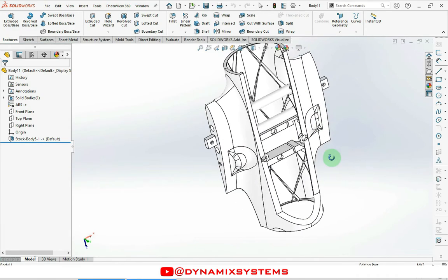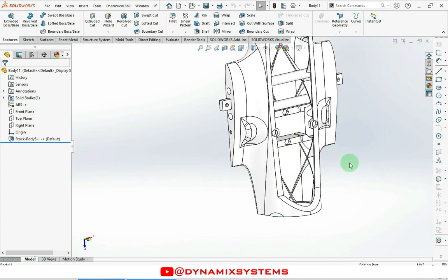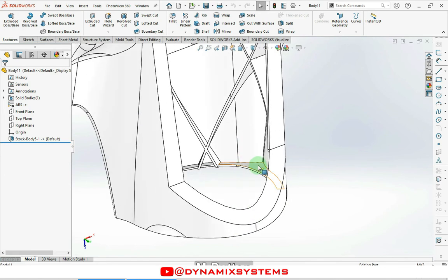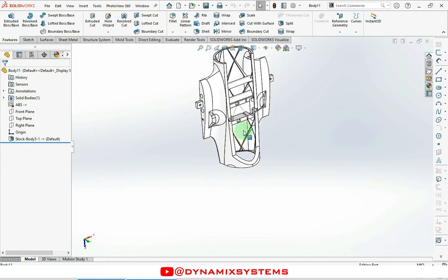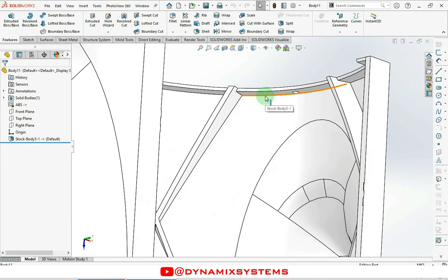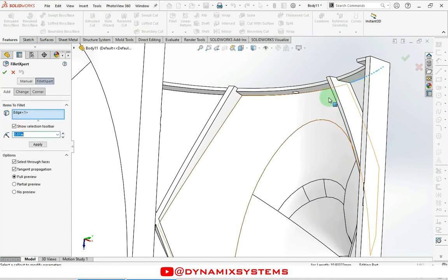So as the example, I work the rest of the process on this file. If I print this from this section as the bottom and this section as the top, this flange here doesn't need any support, but this one gonna need something to make this flange print on. And I simply, by adding some fillets, solve the problem of that. 3 millimeters. Okay.